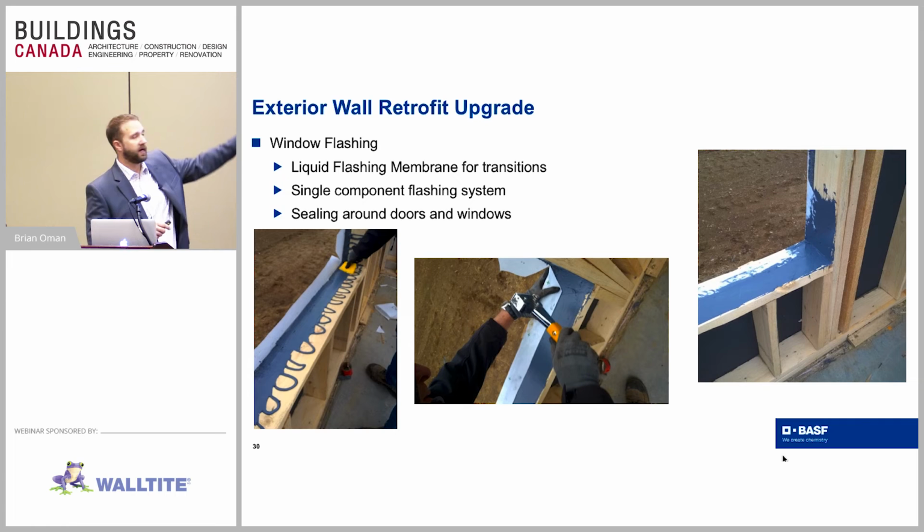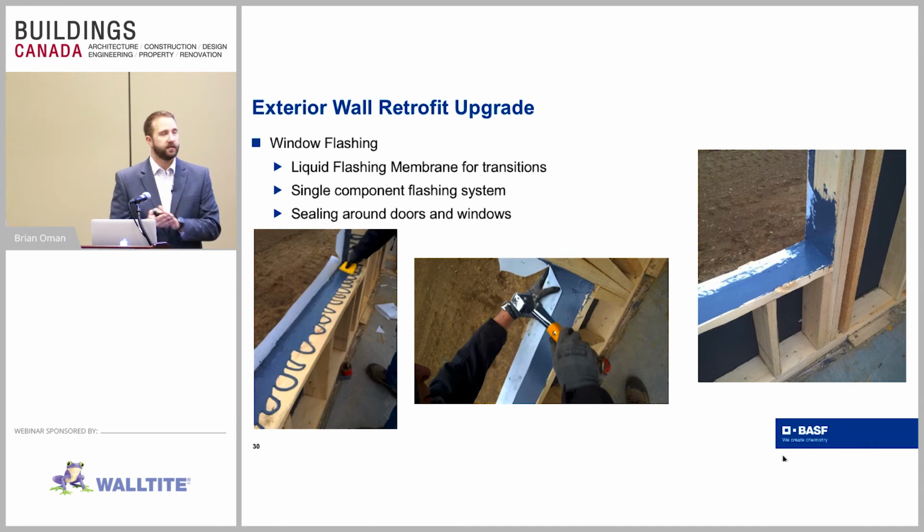So this is actually put on with a sealant, a caulking gun. It's spread out. In this application, they do have a wrap weather barrier. That wrap weather barrier in this case is actually integrated. It's put right into the wet sealant. It's fastened in, and then the edge is terminated with some more sealant. So now your flashing is directly integrated into your weather barrier.